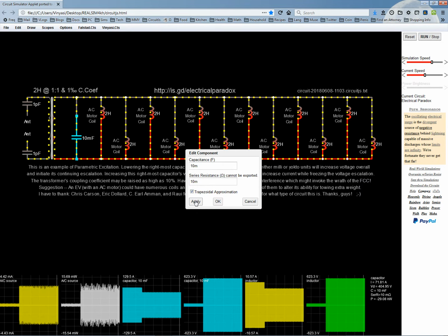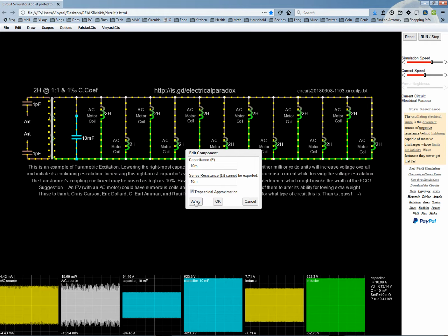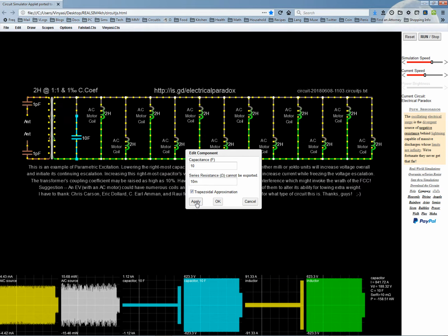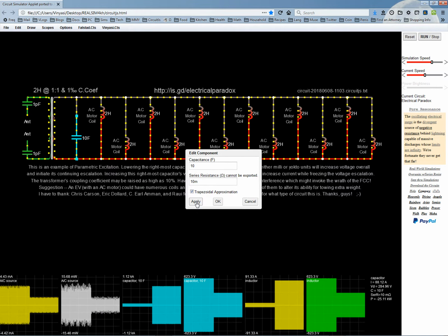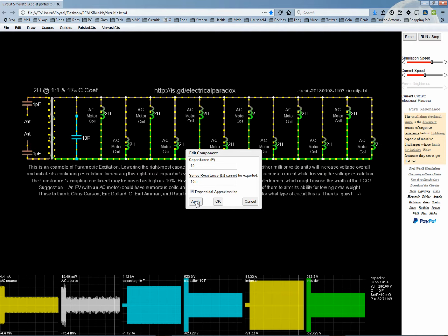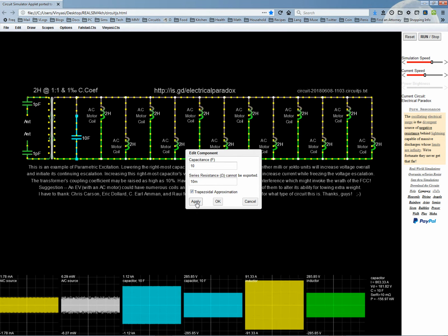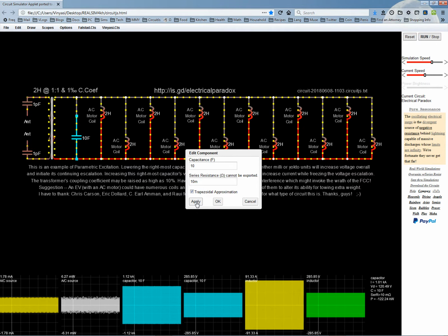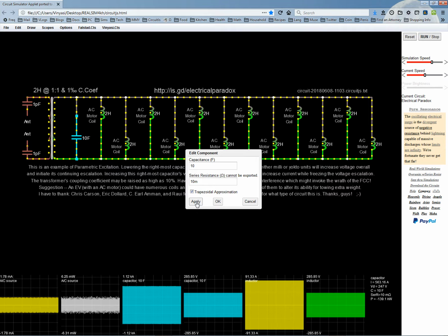Oh wow, that's a lot of volts, but that'll come down. So the system has to accommodate high voltage, because higher voltage and higher amperage than whatever target you're shooting for. So now I got 90 amps, which means I'm going to have a lot of volts. 285. Yeah, that is a lot. Normally for accelerating a car, you might run it at 200 amps, and cruising might be 50. So this is a little excessive for cruising, more like slightly speeding up in traffic.